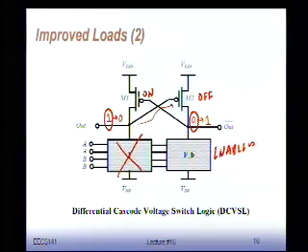So you get a complementary nature between the two. We don't have the same thing that happened in ratioed CMOS. By adding that feedback, we can actually turn off the load at the end of the action, which is really the beauty of this thing. It doesn't have static power dissipation. It has a lot of weird things happening in it. Obviously, you have that feedback. You first have to fight the feedback, which is always going to try to prohibit you from doing something for a while. But when you can convince it that it should move, and you have to work hard on that, suddenly it moves really quickly because that feedback loop is amplifying the thing, and it goes from one state to the other almost in no time. So very sharp transitions from one state to another.